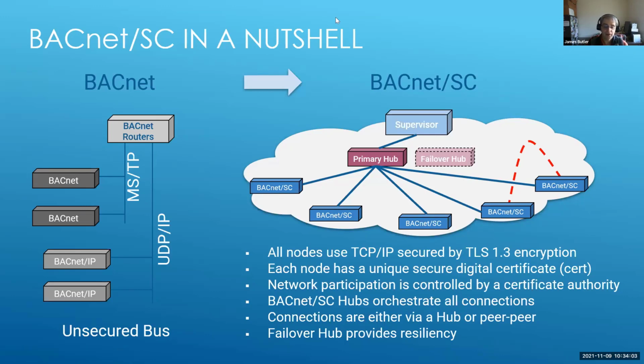The student doing a little project can't just walk up to your IP network and start talking to your BACnet/SC devices. So this is a good thing from a cybersecurity standpoint, but of course it places a burden on the building owner to manage the certificates for the building owner's facilities.